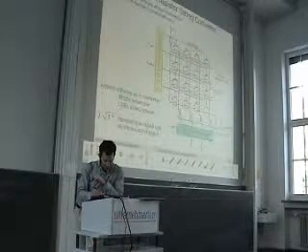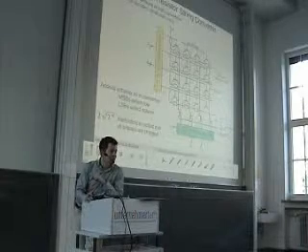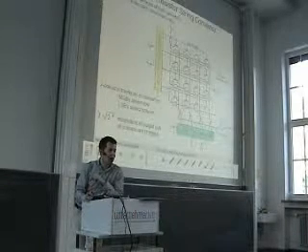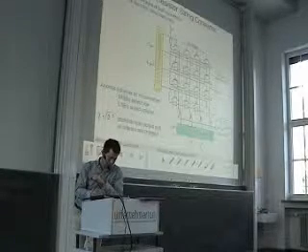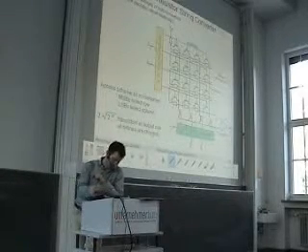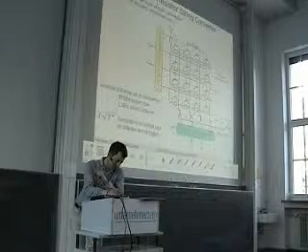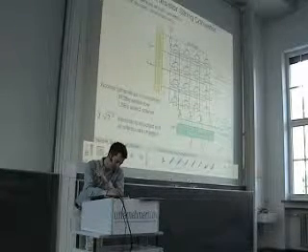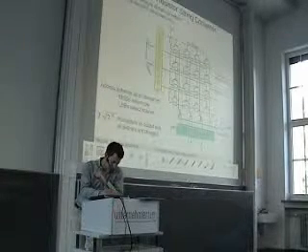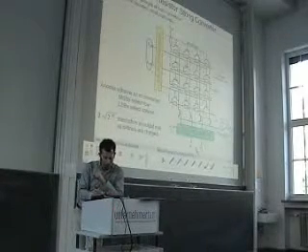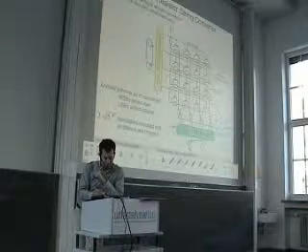Both of these decoders have now only half the number of bits that we would use in a basic resistor string. So here we have a 4-bit structure, but you can see that we have only 2 bits at the row decoder and only 2 bits at the